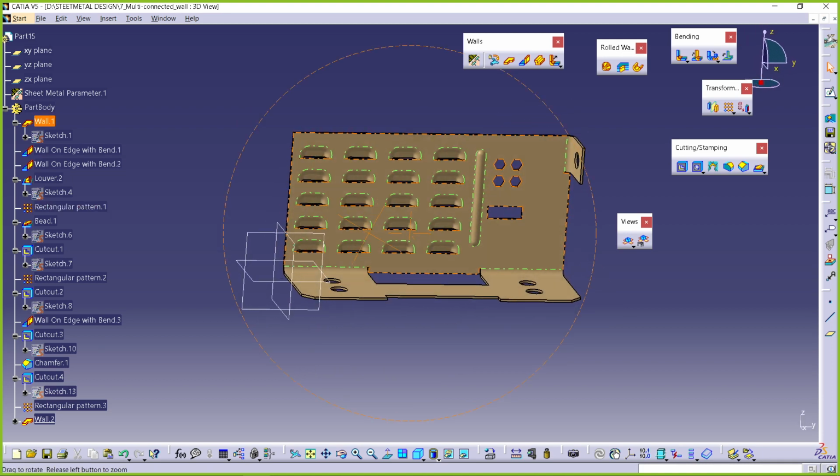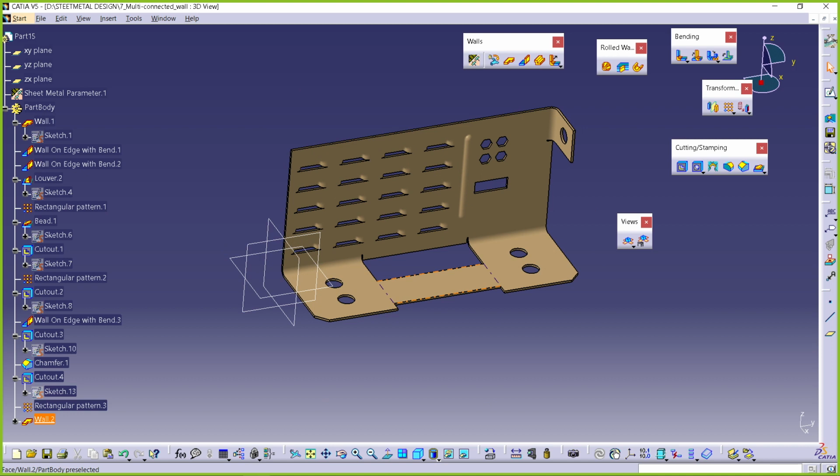Hope you got the concept of why you would go for deactivating the flat view, and what the benefit is. Okay, by deactivating the flat view calculation, it will increase the feature generation speed. Whatever feature you generate, it will be created very fast.